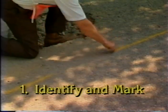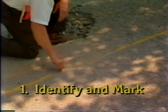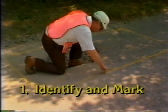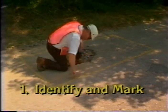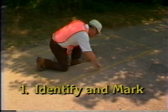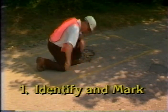1. Identify the area which needs to be repaired. Mark the area to be cut out with spray paint or chalk. Remember, the marked area extends back into sound pavement and has squared up straight edges.